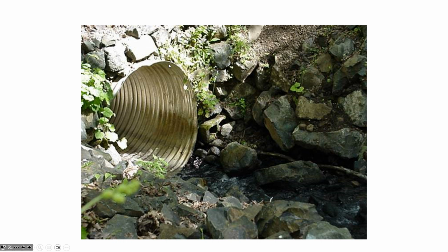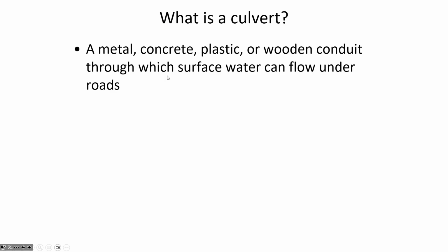But you want to have a compactable material on the underside of the pipe, because you wouldn't want to have just a single point of contact. If it was completely rigid, then it wouldn't be able to develop as much strength as if the soil underneath is all well graded and compacted, resisting the downward force with upward force on the underside of the culvert.